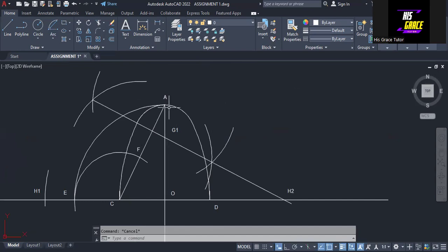All right, so we want to join them together to become one. We have 4 arcs here that we want to join together. So we select them one by one. Okay, and then type join on the keyboard and then press enter. Let's see. So it has become one. Okay, so that's very good.